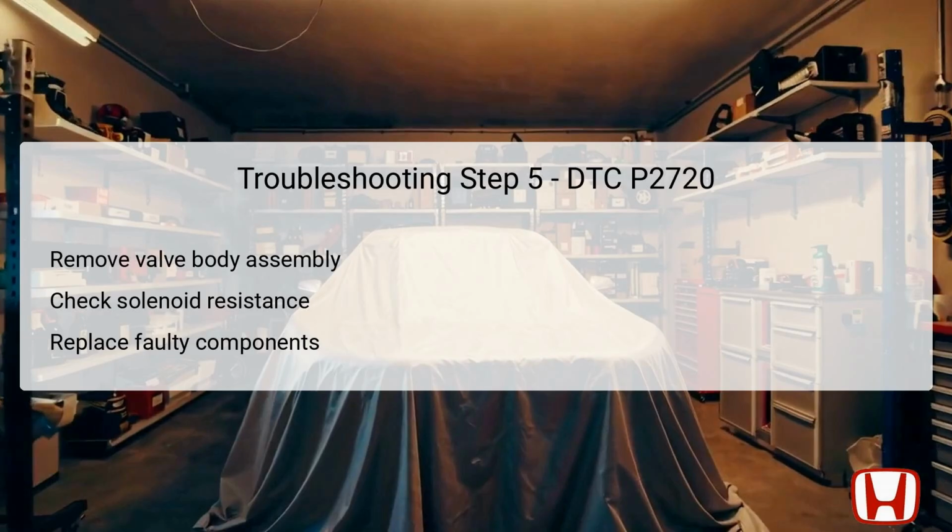Then, measure the resistance between the specified points in accordance with the guidelines. Ideal resistance should fall within the range of 4.6 to 6.3 ohms. If this measurement is achieved, the solenoid itself is functional, and attention should turn to replacing the solenoid wire harness. However, if the resistance falls outside this range, it indicates a faulty CVT lockup clutch control solenoid valve, which necessitates a replacement of the valve body assembly. Thorough identification of the faulty component is critical in restoring optimal performance.